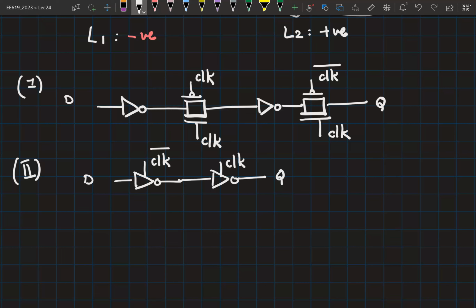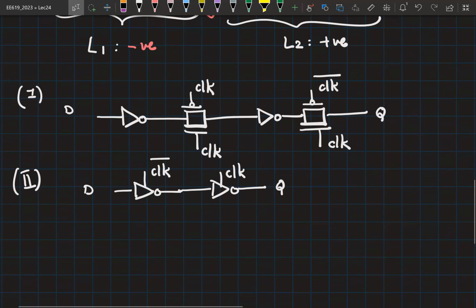Then we will bring in clock skew into picture. We'll still analyze what is happening to these flip-flops. And finally, if there is a finite rise and fall time, or if you actually had a simulation tool and you wanted to simulate and find out the setup, hold, and clock to Q propagation delay, that setup we have discussed in the last class. So the same simulation setup you can use for any of these circuits. Okay. So let's start by analyzing this circuit.